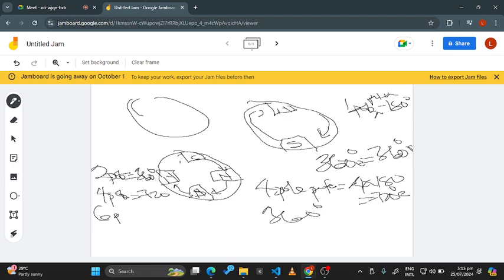Six poles give us 1080, I think. Eight poles will give us 1440, or you can calculate it. Then we can see that while the total mechanical degrees was always 360, there is a relation between the number of poles and the total electrical degrees. Is that okay?